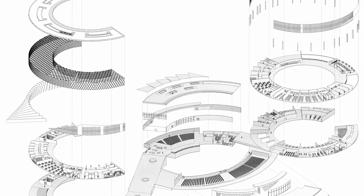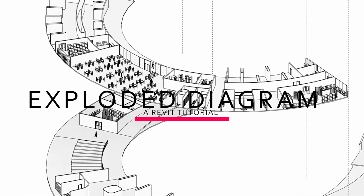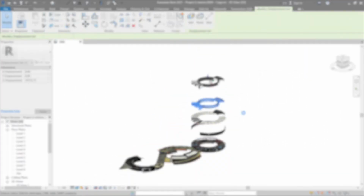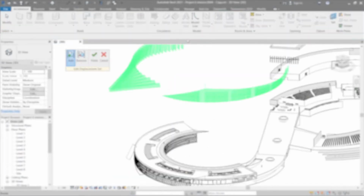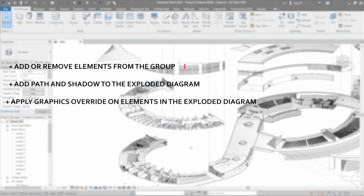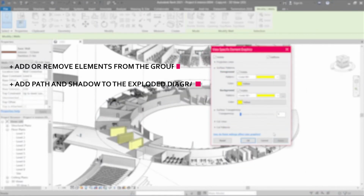What's up, guys? Today I'm going to show you how you can create an exploded diagram for a complex building like this in Revit. We're going to see how to explode groups of building elements, add or remove elements from the group, add path and shadow to the exploded diagram, and apply graphics override on elements in the exploded diagram like halftone, transparency, or even change color to highlight specific element in the diagram.